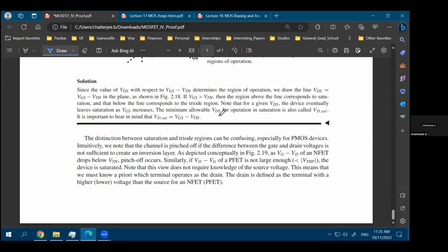Exactly. So how that happens is that we already talked about this, that VDS is much more than zero. It's a positive potential, so it will attract charges. And as it is attracting charges, you have a particular amount of inertia. So let's say you have some charges going from left to right. You have inertia, you have electric field, even though this is a depletion region. Just because of that inertia, they will go through this depletion region and will be collected at the drain.